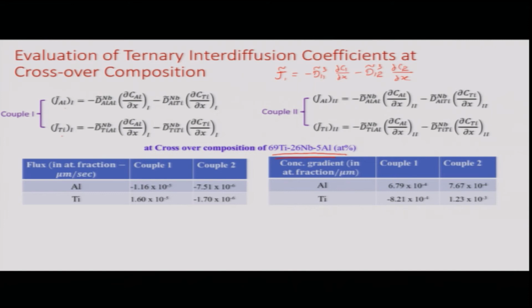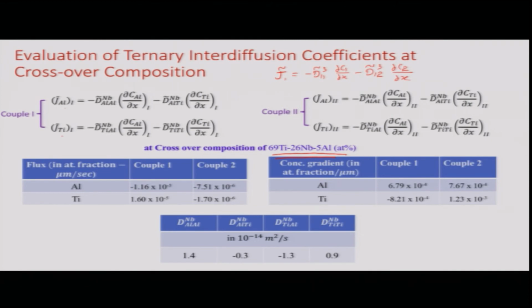of the components, and so the unit of flux will change and the unit will be atom fraction micron per second. But for this we have assumed that the molar volume is constant, and we do this because it is easier to work with the atom fractions. And assuming molar volume constant, the volume fixed frame coincides with the laboratory fixed frame.